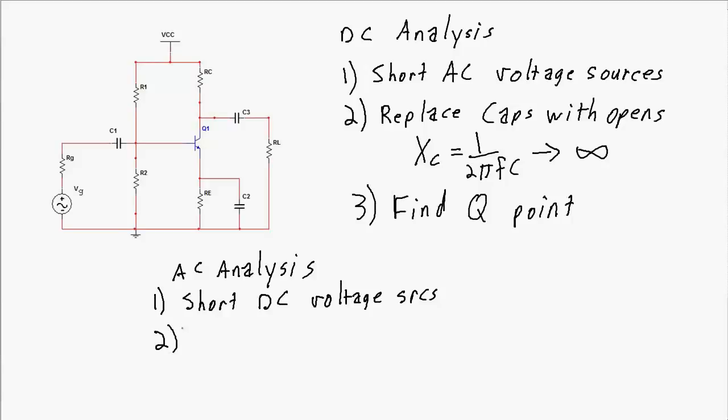Secondly, I am going to replace all of the capacitors with shorts. I'm assuming that I'm at appropriate frequency and appropriate capacitor values that I can do that. Replace the capacitors with short circuits.